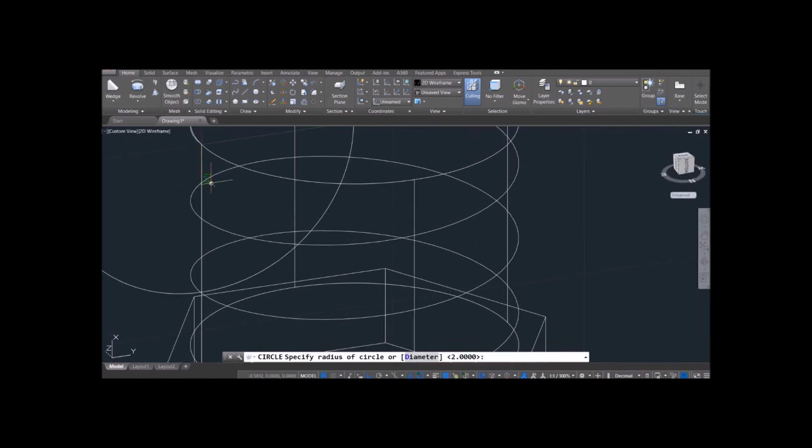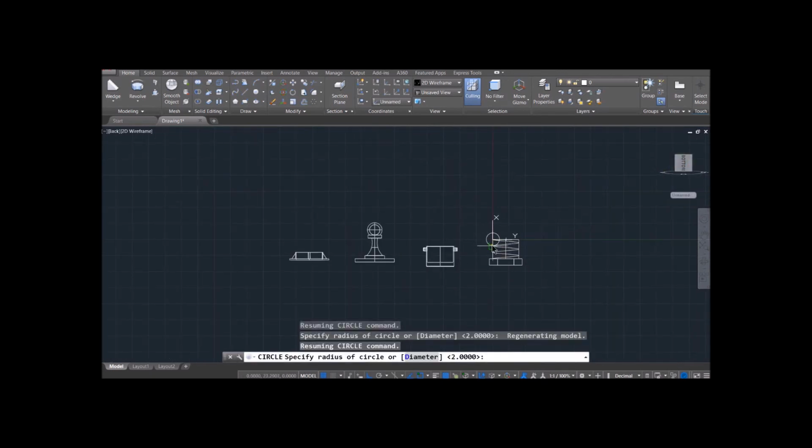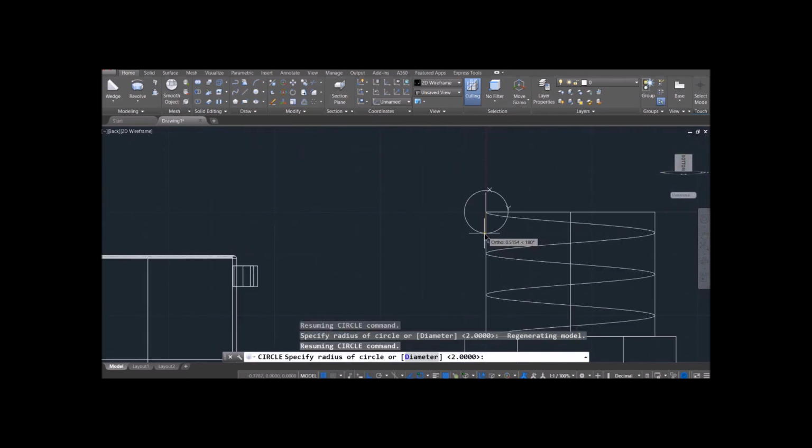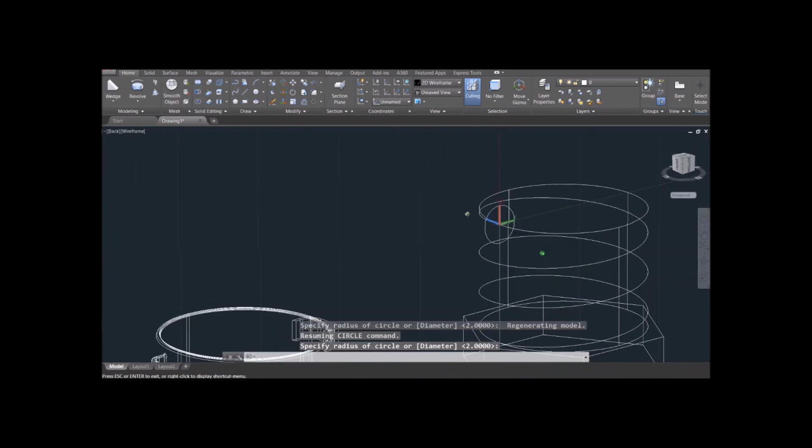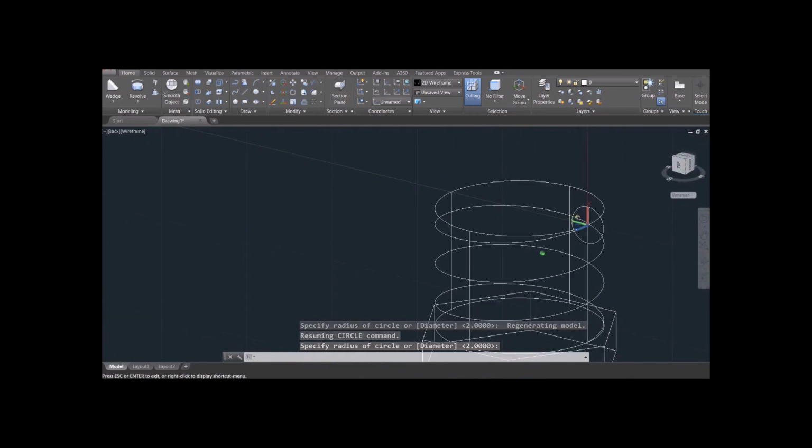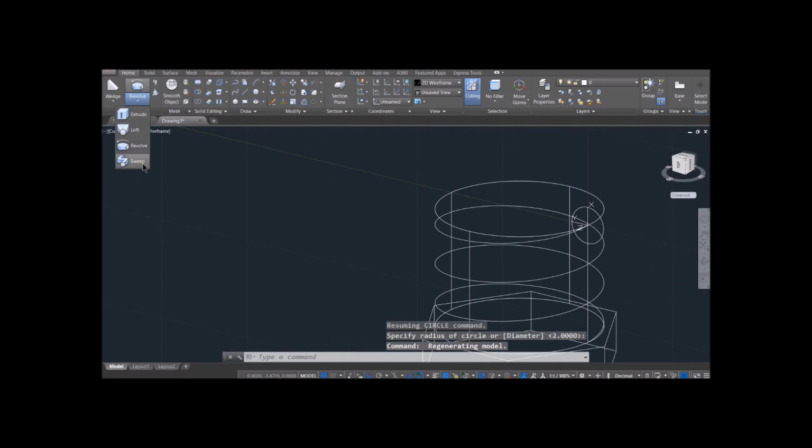You might want to reorient it so you can really tell where the halfway point is, and you should probably know the distance between threads. Distance between threads here is 1. I'm not going to set it to exactly 0.5 because it would overlap, so just a little bit smaller than 0.5. If it intersects itself, it will not do this path extrude.